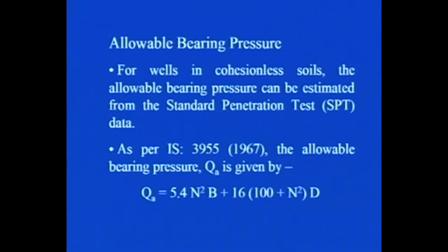For wells in cohesionless soils, the allowable bearing pressure can be estimated from standard penetration test data. As you have already studied in the very beginning of this course, there are various field tests and the data of those field tests can be used in the analysis and design of various foundations.